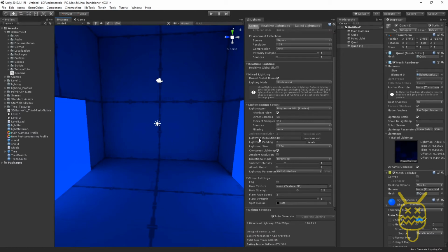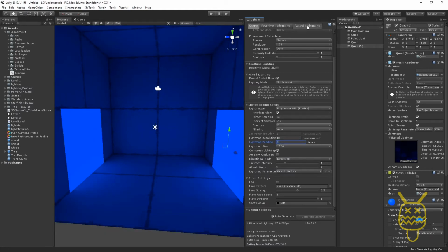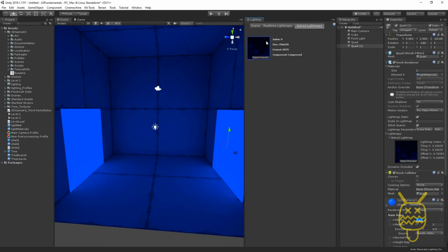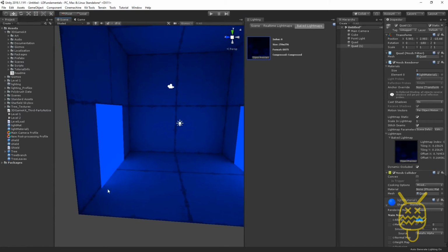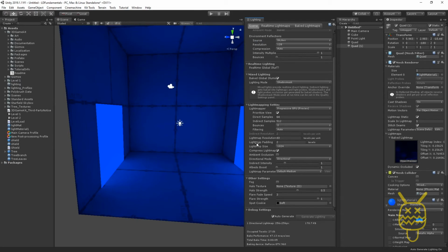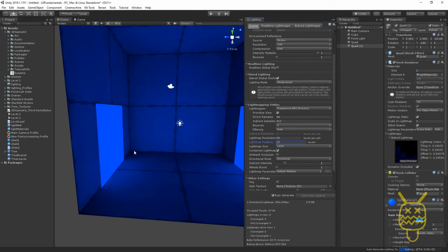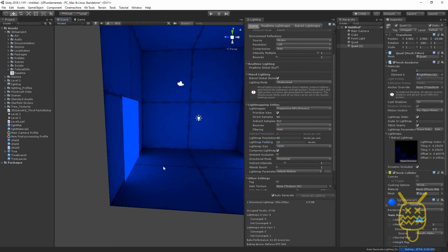The next thing that you want to do is down below, you have the light map padding. This is going to be used when the object is baked. If you notice here, you have an object where the UV is being baked out. If you have bleeding, where one object has some color that's not supposed to be there, you can actually increase the padding to about 10 to 20, and anywhere in between there will usually make sure there's enough space between the UVs that are laid out to be far enough apart.